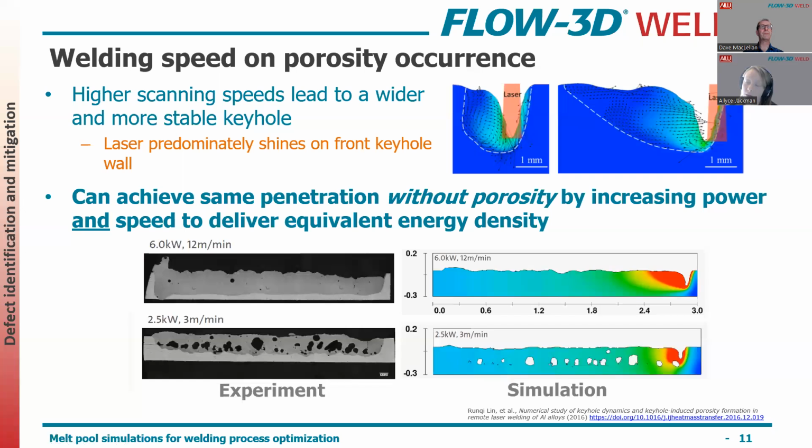It does kind of change the process dynamics, what effect it has on thermal gradients and cooling rates, might impact your mechanical properties. So it's not necessarily the universal answer to all porosity, but in this case, it proved to be a very good solution.